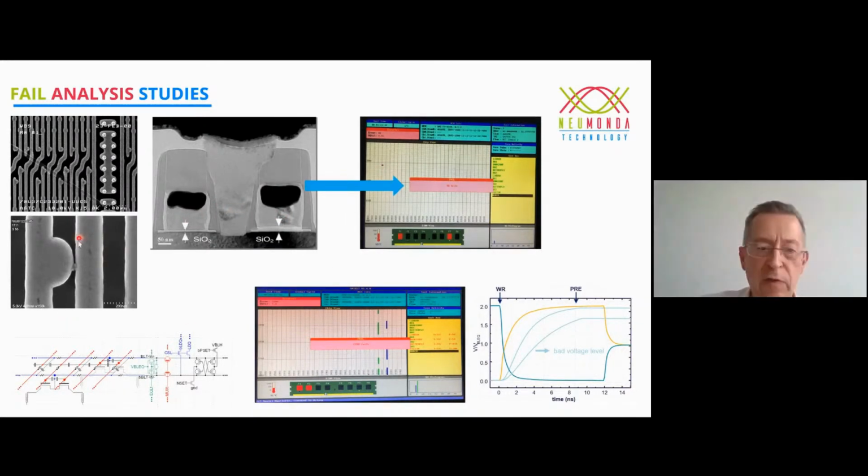Or burn-in experiments. This is a classical fail while you are doing burn-in testing. You want to burn it through at this 125-degree initial burn-in testing, because maybe it passes at the customer, but after 3 months, it gets lower resistance and then it turns into a fail. So we can test now at gigahertz. We are getting much more sensitive to such issues and can detect them maybe at gigahertz, which you cannot detect at 5 megahertz. So such experiments, you need volume, and this is the reason for this pilot factory.